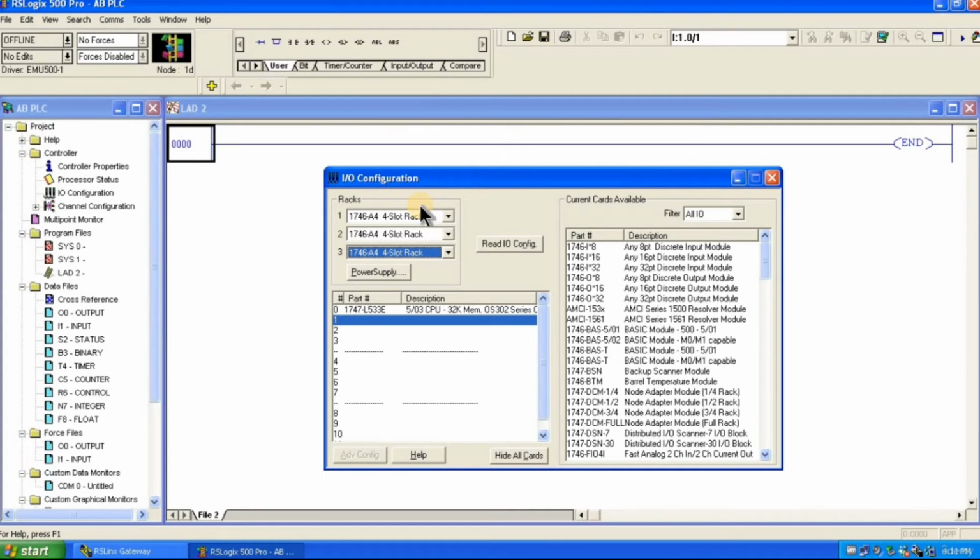For that, some communication connectors are also available with the PLCs, right? So right now we don't need the 2 additional PLCs, right? So initially we are just using, okay, here it's very simple now. Just click on IO rack not installed, then it will disable automatically, right?